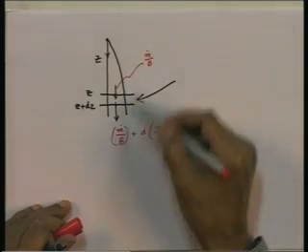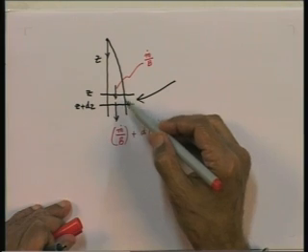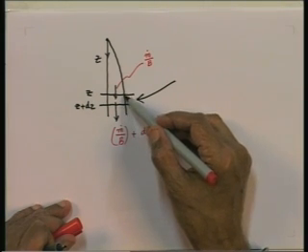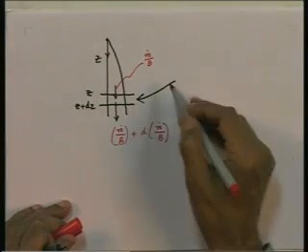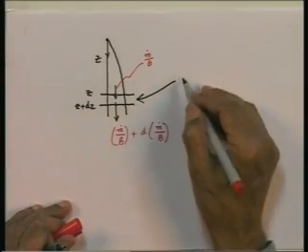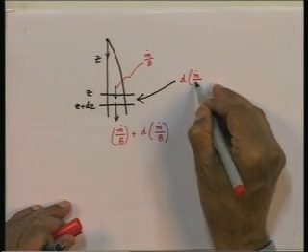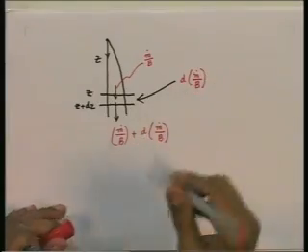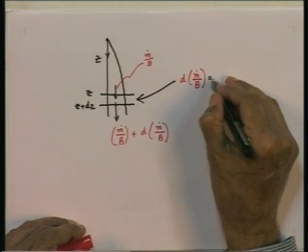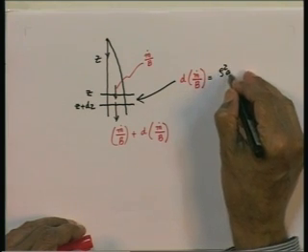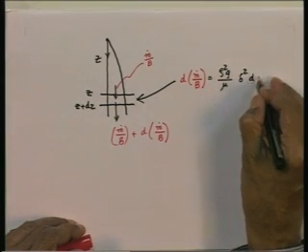Obviously the difference between the two has been made up by condensation which is taking place from z to z plus dz at the liquid vapor interface. So, this quantity d of m dot by b has the expression rho squared g by mu delta squared d delta.